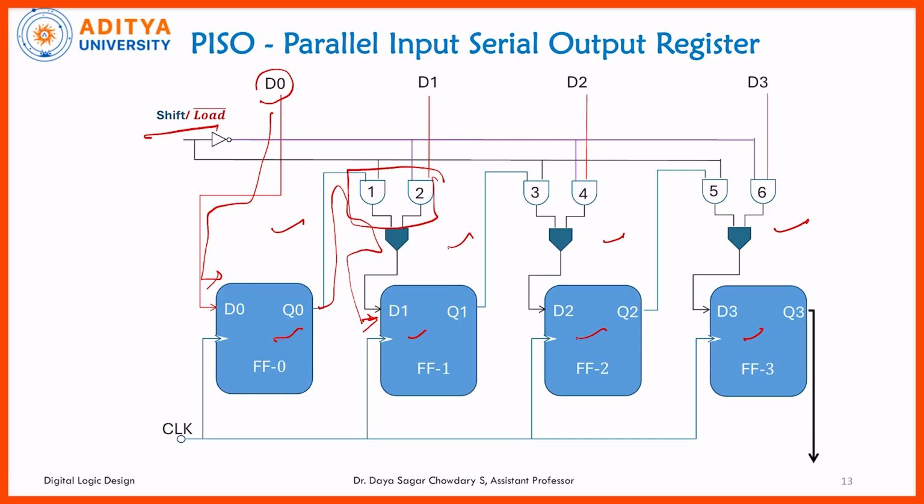We already checked this in the first slide, the sequence of the flip flop with the logic. This is the logic, the combinational circuit. We are simply connecting it to all the flip flops. Depending on this data, we connect the data to the AND gates, and the output of the previous stage is given to one more AND gate, and finally we connect this entire thing to the next stage.